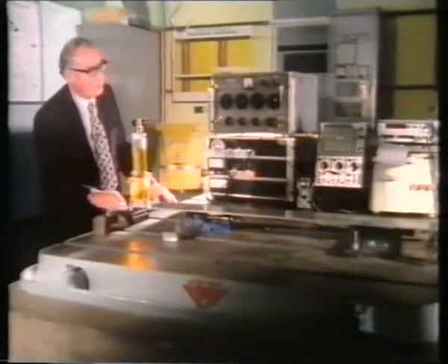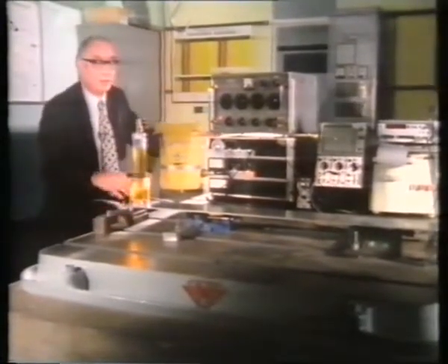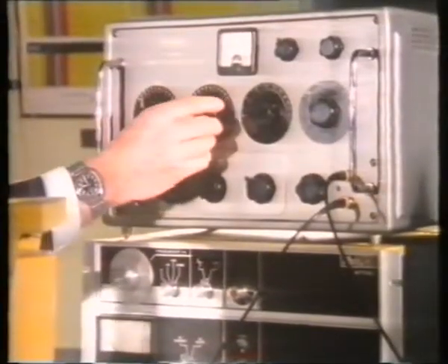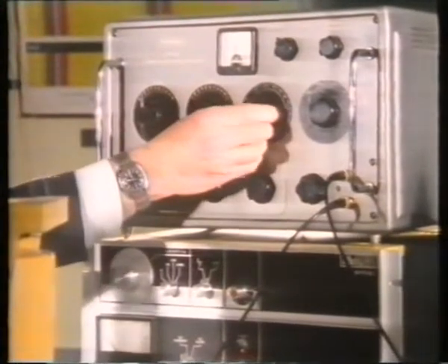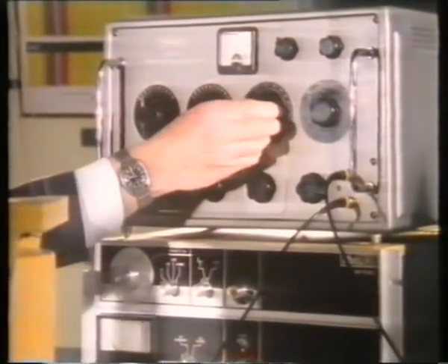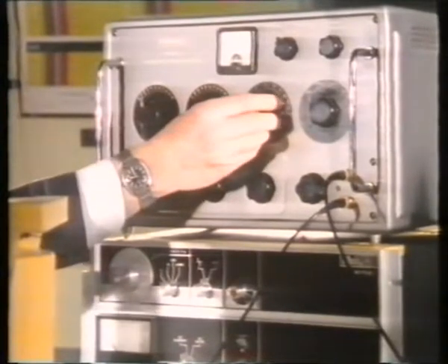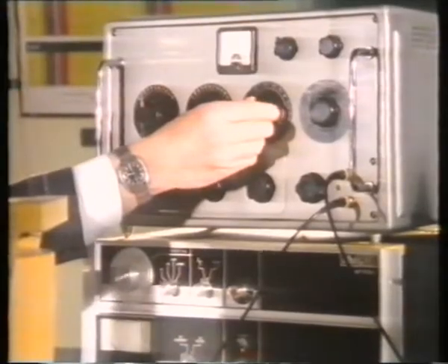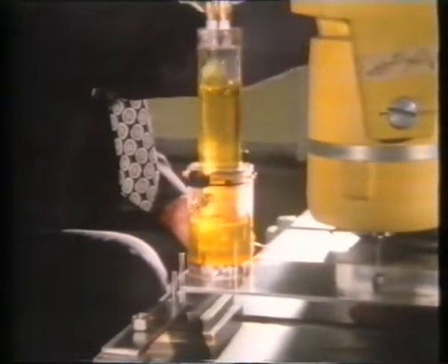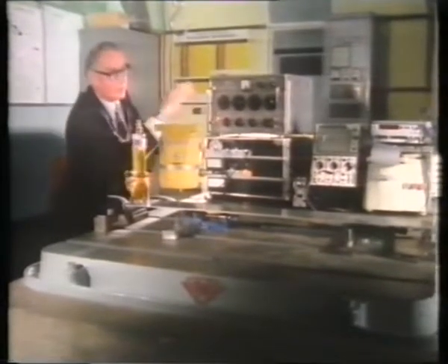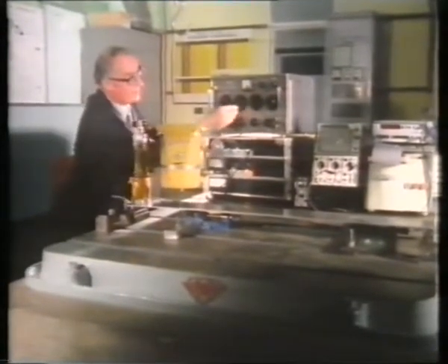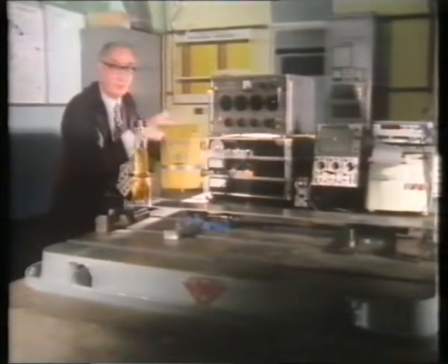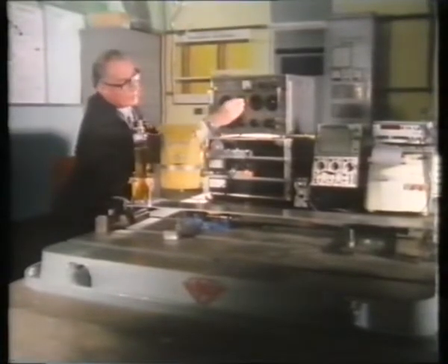So I'm now going to sweep through the frequency range to pick out the 2 peaks we would expect to see for a 2-degree system. I'll sweep the frequency range up through, this is 11 hertz, 11.1, 2, 3, 4. Here we have the maximum excursion, about 11.7 hertz. This is the first peak. I'll now carry on increasing the frequency to find the second peak. Meanwhile, I go through the trough between the 2 peaks, around about here.